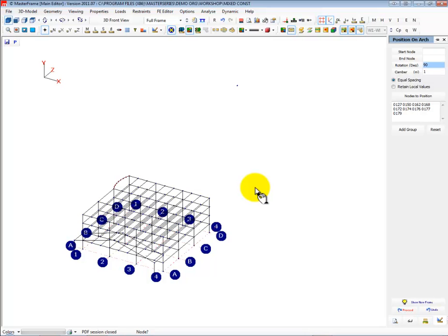So that's how you curve your members. You create facets, and you don't have to get a massive number of facets to get a realistic curve from an analytical point of view. In some cases, 2, 3, 4 segments is more than enough. You obviously want one right out at the tip so that you get the lever arms you require. So I would suggest you're talking about probably 4-5 facets.